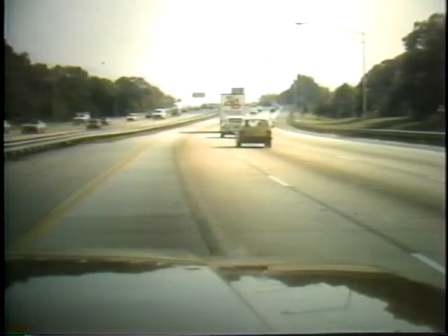One of the most powerful delineators is the pavement itself. Drivers are uncomfortable when they cross joints or differing pavement types. Rehabilitation designs need to correct differences in the feel of the road to the driver. When these differences exist, positive delineation devices should overcome the negative effects of the pavement.